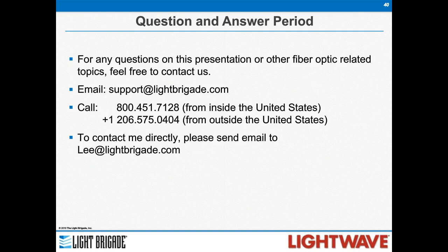So what type of source would you use for multimode testing? Is a VCSEL okay to use? Yes, a VCSEL is okay to use, and an LED is okay to use. Just make sure, if you want accurate results, that it's an EF compliant source, encircled flux compliant. If not, use your launch cord, your test reference cord with a mandrel, so that you have a nice restricted, repeatable launch.